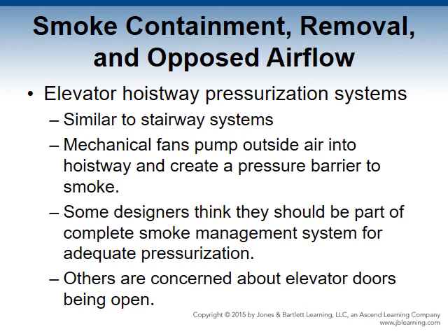Elevator hoistway pressurization systems operate similarly to stairway pressurization in that mechanical fans pump outdoor air into the hoistway and create pressure barriers to prevent or substantially reduce the smoke intrusion. Some design professionals think it is better to operate these systems as part of a complete smoke management system that includes zones or floor-by-floor systems, because standalone pressurization may not be adequate.